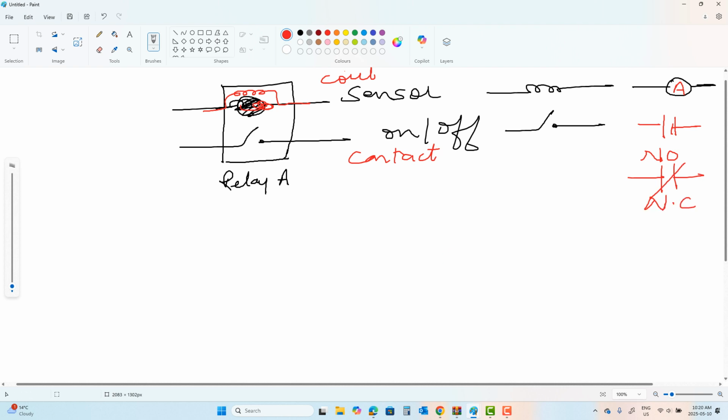Okay, so what happens when the sensor senses motion? Car came in. Okay, the sensor sensed motion. What happened? The contact went from open stage to closed stage, and what happens? The light goes on. But there is a delay switch. Maybe there is 60 seconds delay or 3 minutes delay that has been created. 3 minutes later, once you are already in the house, the light goes off.